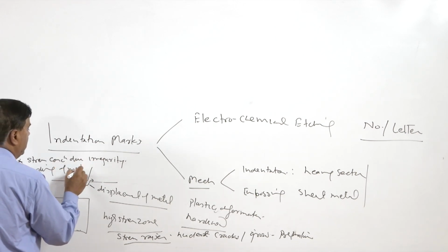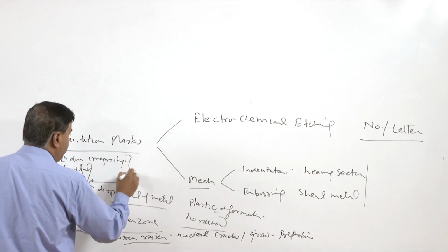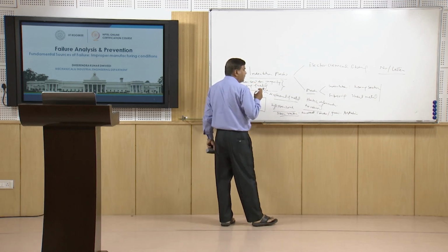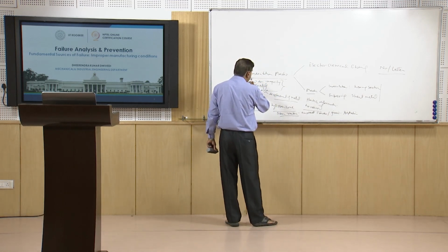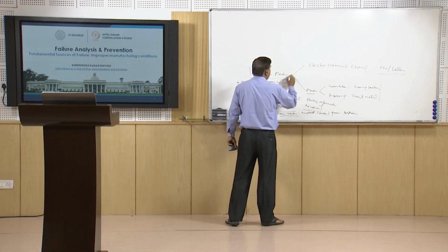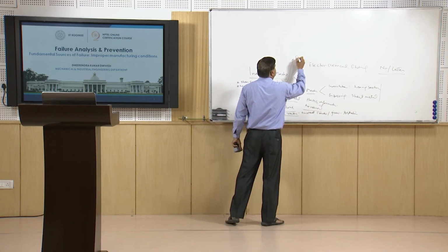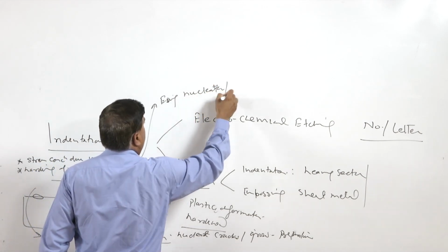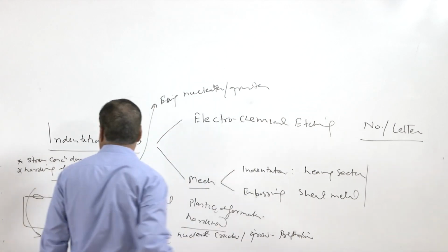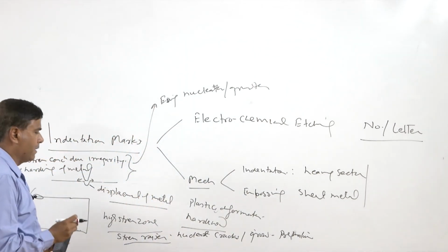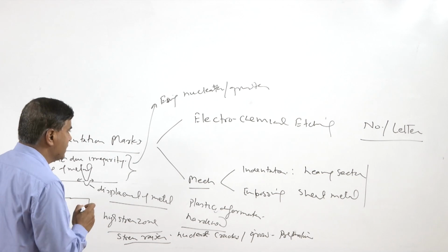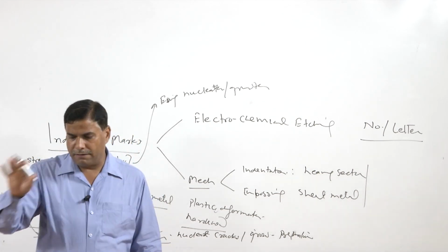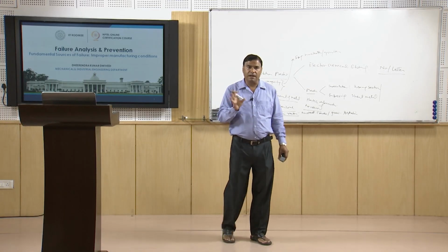Hardening of the metal also reduces its tolerance for the nucleation and growth of cracks. A combination of both these factors provides easy nucleation and growth of cracks, which can lead to failure of the component, especially in those components where the stresses acting on the surfaces are maximum.